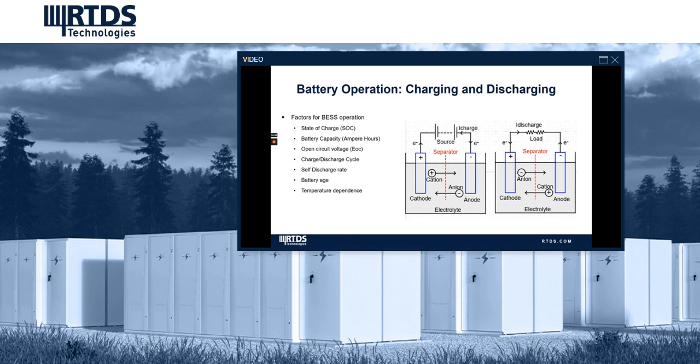In charging operation of the battery, energy is supplied to the battery cells from an external power supply. The flow of ions between the electrodes through the electrolytes allows charge to be built up in the battery. In the battery's discharging mode, the flow of electrons moves energy through an external load, allowing the stored charge in the battery to be dissipated.